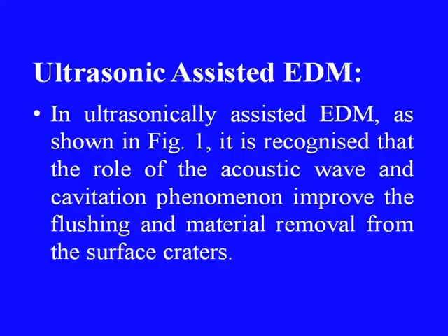In this process, the surfactant molecules act as a static barrier to separate the agglomerated aluminum powder and disperse them within the dielectric, thus improving the surface finish. Now, let us move on to another process that is called ultrasonic assisted EDM, also called UAEDM. This is another hybrid process of EDM.